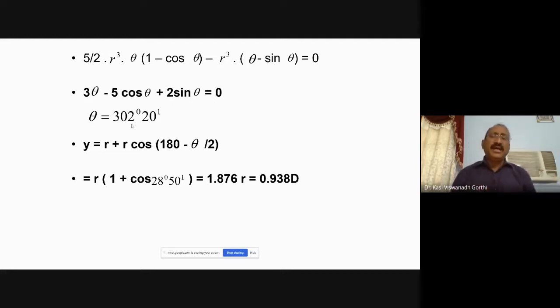There is a difference because both these formulae, let it be Chezy's formula, let it be Manning's formula, both are semi-empirical formulae which have been developed based on several different criteria. So Chezy's coefficient in the case of Chezy's formula, Manning's coefficient in the case of Manning's formula are interdependent on various factors. As a result of which, you have the value of theta different. While using the Chezy's formula, you have the value of theta different, another value while using the Manning's formula.